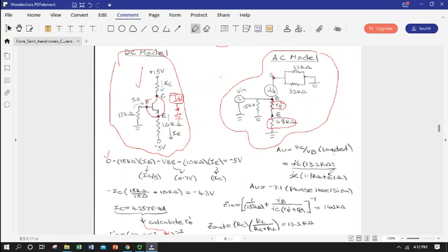So we needed our 61 ohms down here in our V sub B expression. So we can basically go from ground, and we're going to drop by the collector current flowing over this parallel combo, and that will be V sub C, and that's this expression.